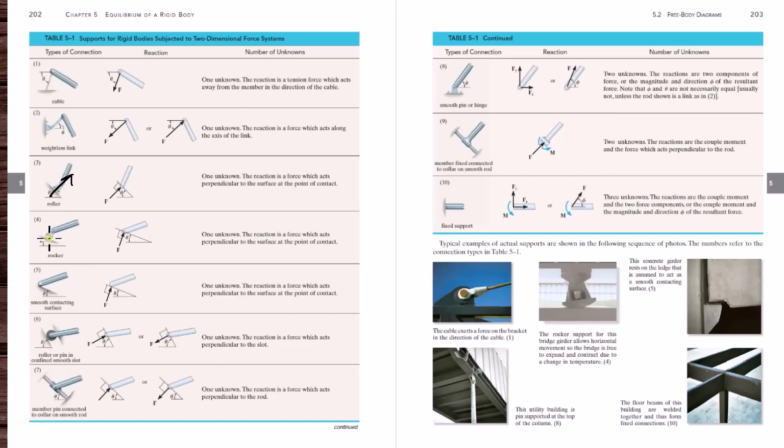Motion in this direction. It's not preventing motion in this direction, and it's not preventing any rotation. Now, as far as motion into or out of the page, that's not a part of the problem. Motion or bending into or out of the page should be negligible, or else you need a roller in 3D. But you can extend all of these to 3D with no problem, right?